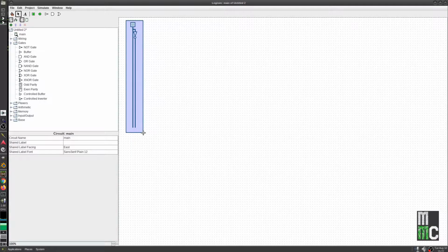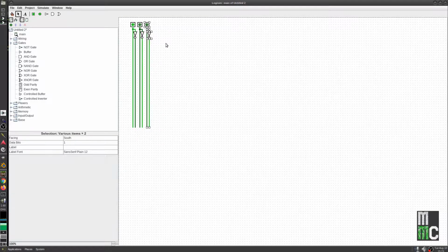So I'm just going to drag a box by selecting up here, holding down and dragging to open a box, select, and I'm hitting Control-C for copy, and then Control-V. Now when you do this, you want to make sure you don't get any sort of wires coming out of here. It's very easy to do. Anytime that I get a green circle you see there, that means I'm on a connection. So instead you want to just click somewhere else and connect it up like this. Same thing, Control-V to paste, drag this one over here, Control-V to paste, and drag my final one over here.